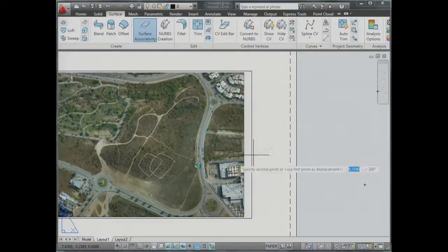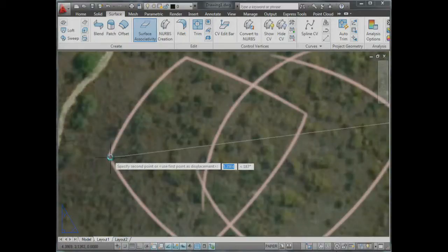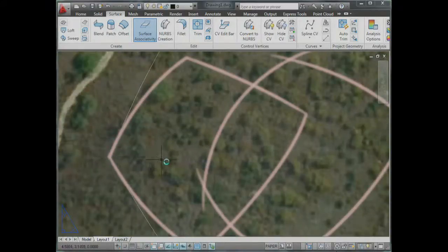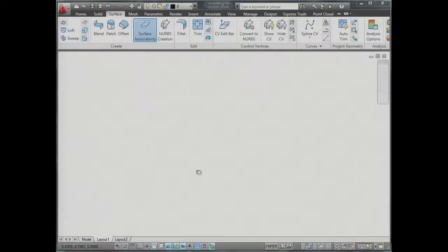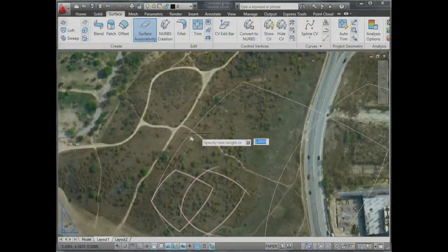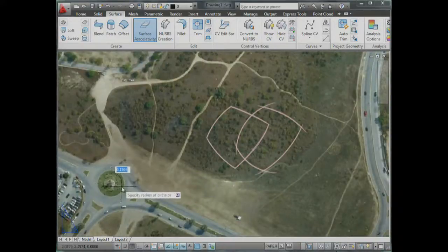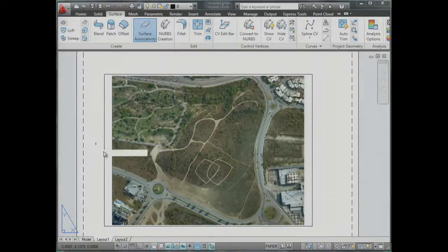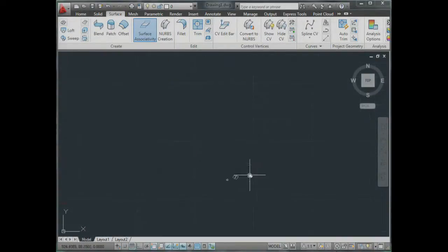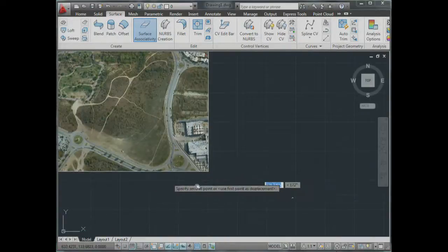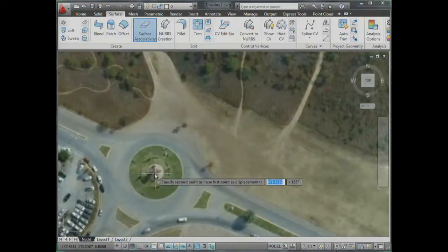So now I'm going to take that information into the right place, and I'm going to use the same procedure I used for scaling the photograph. In this case, I'm going to scale the vectors according to the photograph with reference. It's a very simple way to get everything on track. Now I'll just make something for reference. For example, I know that that's a circle, so I get that information, and I take all that into paper space. Remember that paper space and model space in AutoCAD are completely different environments with different scales, so this is a step that looks a little annoying, but it's something we have to do.